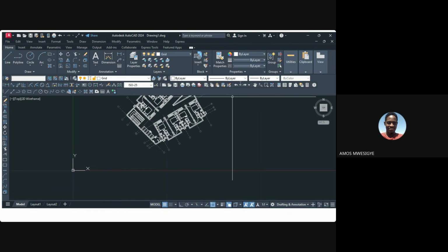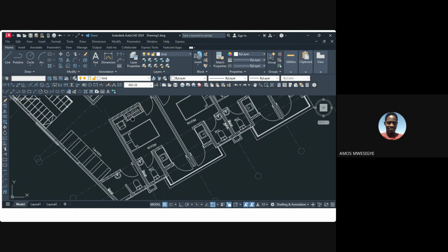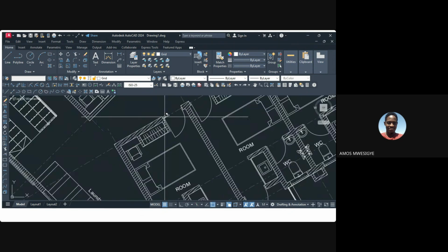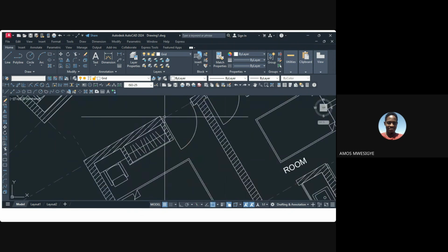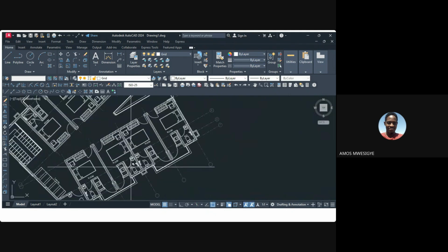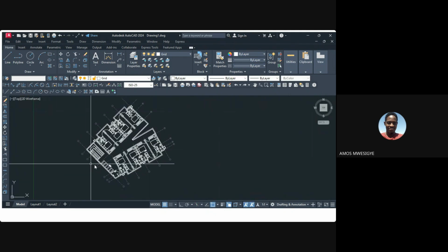This is not really the real dimension of the wall. The wall is usually 150 millimeters, 200 millimeters. When you go to a retaining wall, you can even find 250 millimeters. So we really want to work with a drawing that is a replica, a real representation of the real drawing on ground, on site. So I'll measure that. Let me assume that.